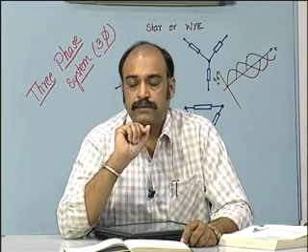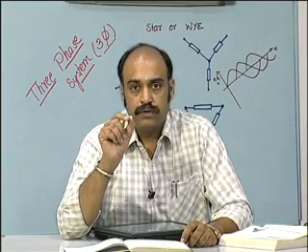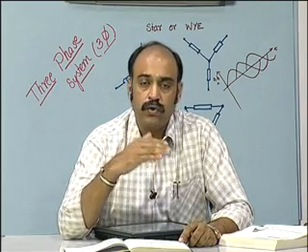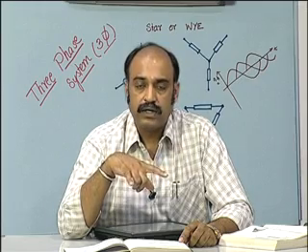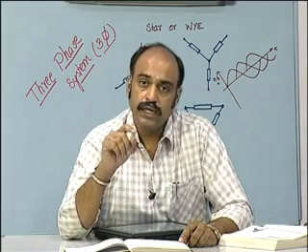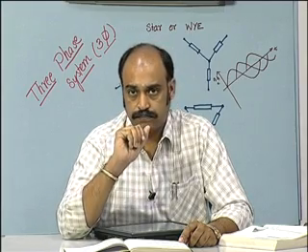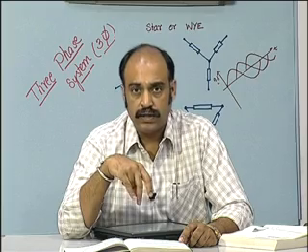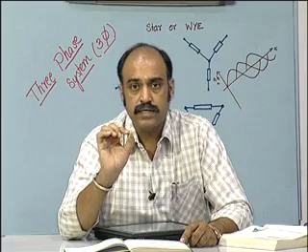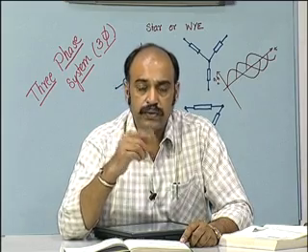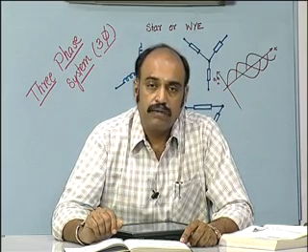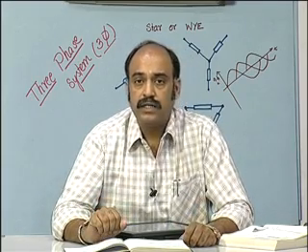They are added in a way such that if an effective value of current I is flowing through the reactive phases, that is the capacitance and the inductance, root 3 times I will be flowing through the resistive phase, that is the actual resistance. Or in other words, if some load current is flowing through the load resistance, that current divided by root 3 should flow through the reactive components that we put in the other two phases.